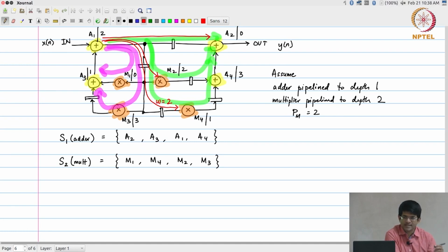Okay. So, there are two options available to you here. Either you just go through this and make sure that you count the number of delay elements properly, or you redraw the original block diagram as a data flow graph just for clarity, so that the exact number of delay elements are easily visible. Obviously there are more edges. I am not going to draw every single one of them over here, you can do that quite easily on your own. So, what I am going to do instead is try and calculate the DF values.